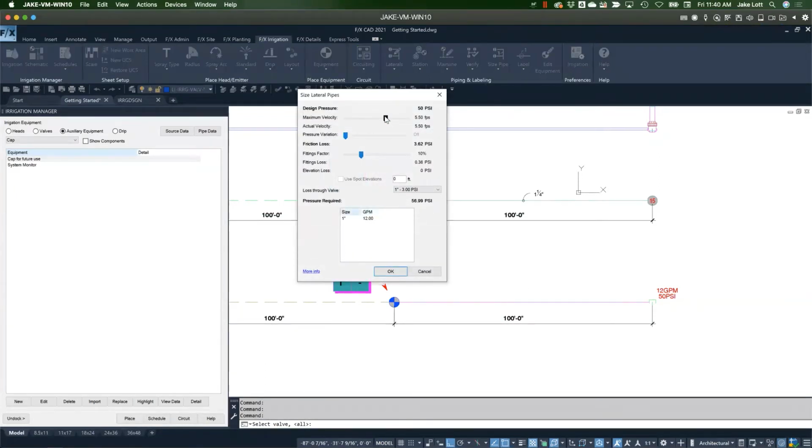And if I look at my book, and I'm using Schedule 40, you're welcome to pull out your pipe charts in the back of the book to follow along. Basically, looking at 12 GPM, understanding what kind of losses and velocities I should be looking at is really what we're looking at here.